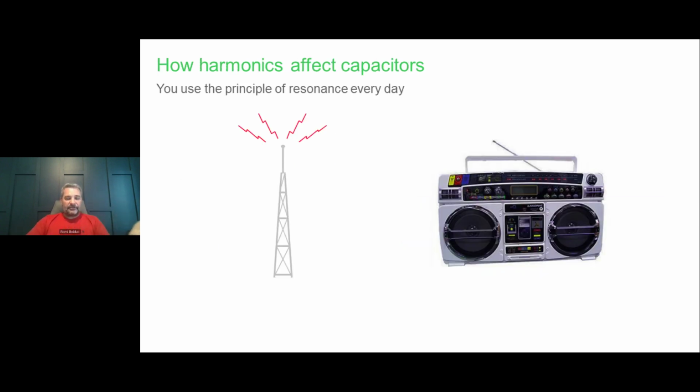And then you can actually have a worse scenario where a standard capacitor bank creates resonance in your network. In a series resonant condition, it can bring harmonics from the utility into your facility, or if it's in a parallel condition, you can actually magnify harmonics. I will try to explain that for you in the next few slides.